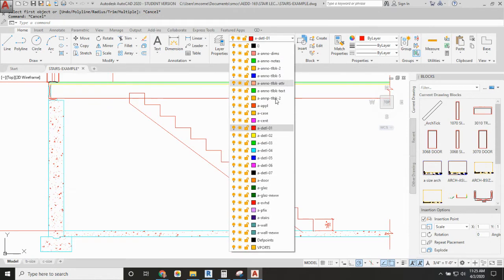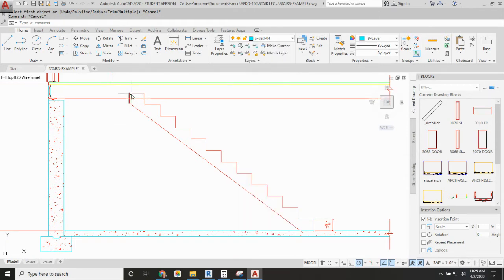So I'm going to switch to a different line weight and show that there would actually be an opening in the floor here where the stringer is hanging on the floor. And we would have two headers side by side that are making up the opening for the floor. And we'd also have the same two headers on the other side, more or less aligned with the nosing of the last riser. So that's the stringer right there, this whole piece.